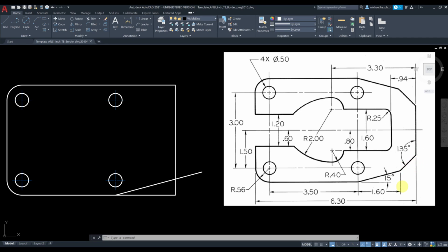For this line, what we're gonna do, let's draw an additional line from the same point along the x-axis, right? You can press F8 for turning the ortho on, so it'll only draw horizontal or vertical. Keep the cursor in this direction, type 1.6, press enter. Just draw this kind of construction line. Escape. Okay, so this intersection is the start of the next line. We don't care about the length of it, but we care about the angle. The angle will be 45 degrees there, 45 degrees there.